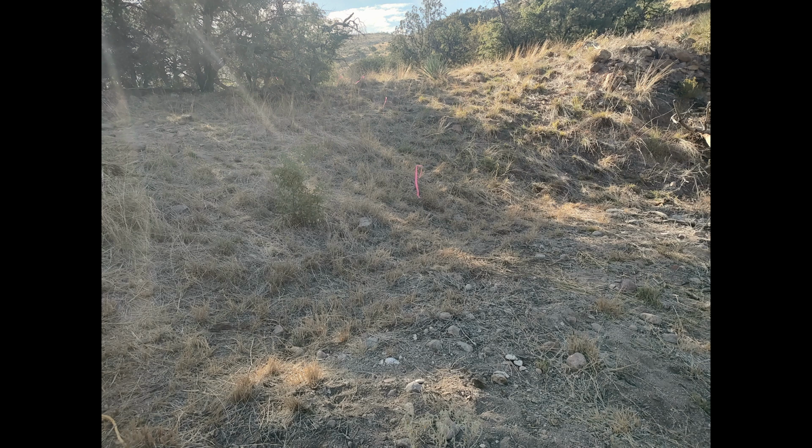To repair the pond, it would be better to build a new spillway where you see the pink ribbons. This is where the dam ends at the other side of the valley. The spillway would carry water away from the dam and down a slope less than 1% to control erosion.